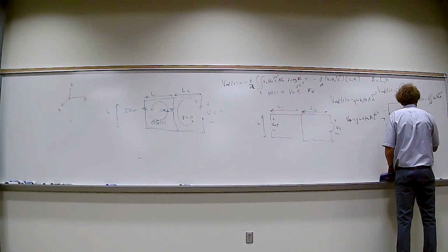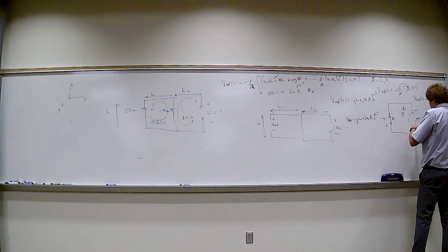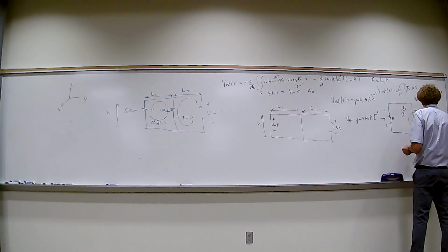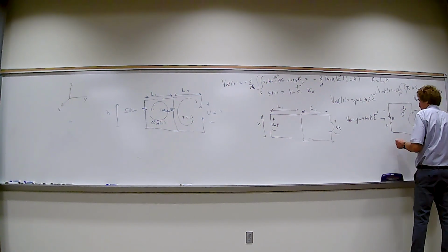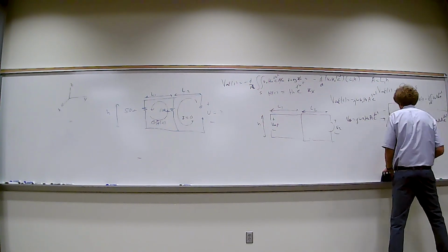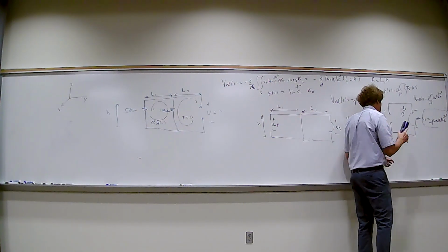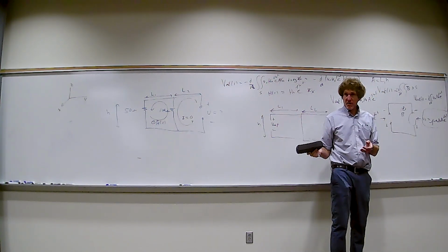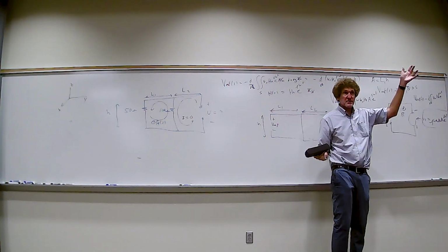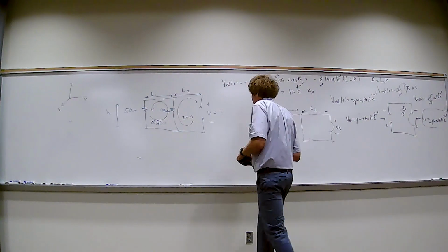It's plus to minus, and my V source here will be equal to, if you look at it, I've got the polarities there, it's just going to be equal to j omega mu 0 H naught times the area times e to the j omega t. I'm going to put a source there, and then I can put the resistance in there. Now, if you look at that source, if I remove the resistance, it still develops the right voltage. Do y'all follow me? The polarity sense. How many see this right here? There's no current.